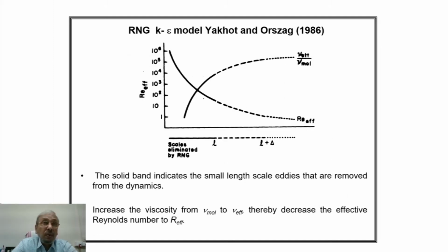So, these models are all very exciting. One can look into them, and they have extensive comparison with the database of Coles, and I have discussed that already in the earlier K epsilon related lectures. Now I will mention two very special models. One of them is the RNG K epsilon model. RNG means renormalized group K epsilon model.